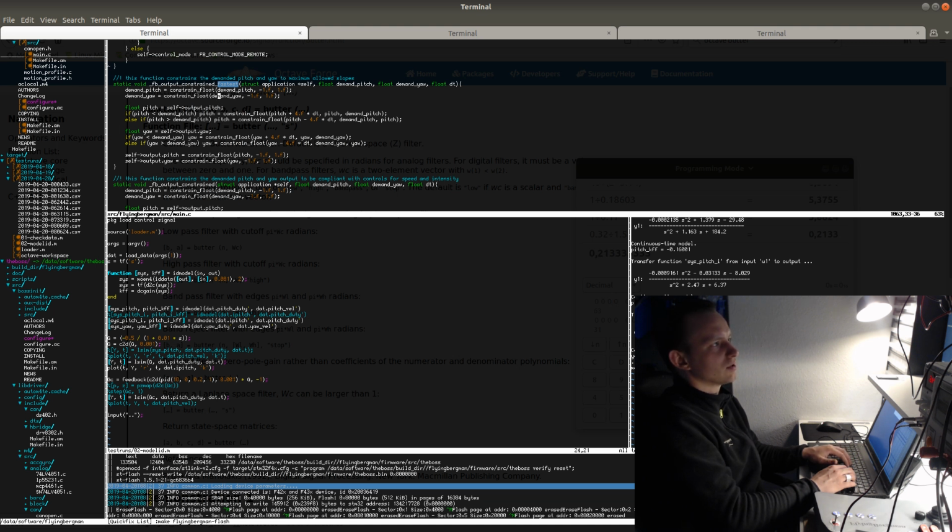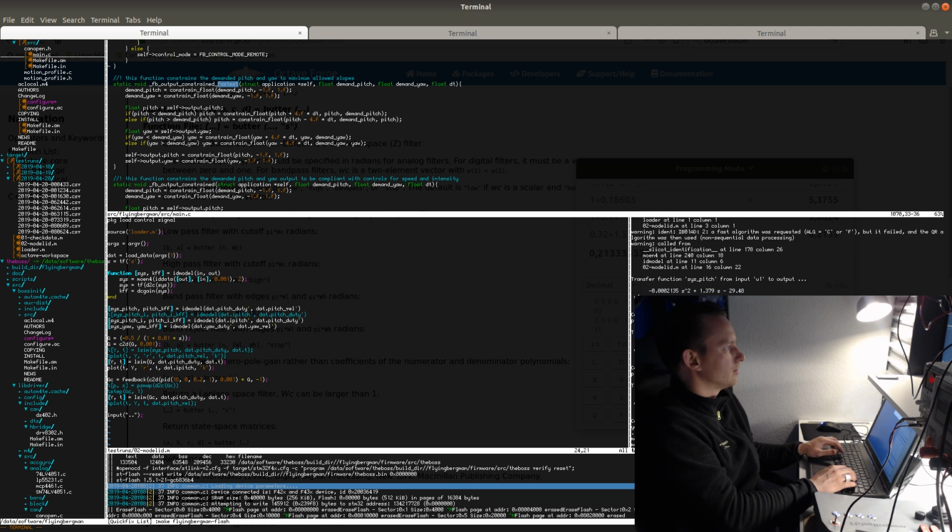And when I'm going to be controlling the current, I'm going to actually remove this, because I'm going to be controlling the current at a much higher frequency than the frequency of the control loop. And this ramp is not going to be necessary anymore. And this ramp is actually the reason why I'm getting this wrong.